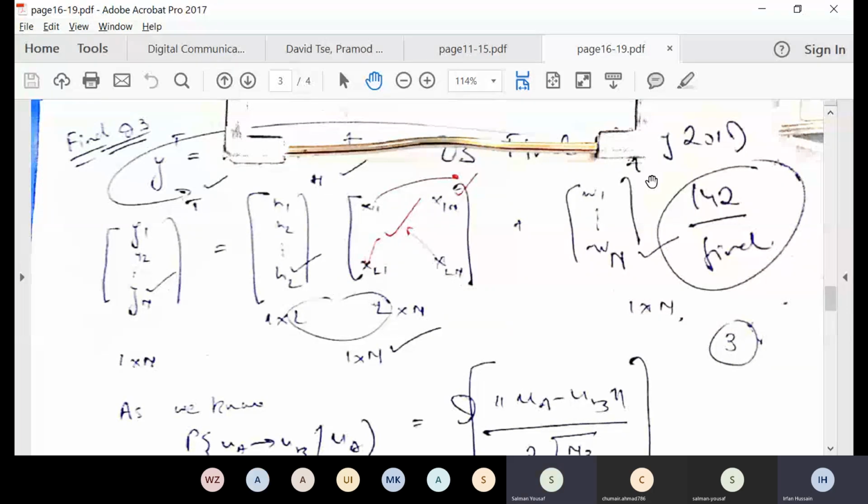I want a little clarification. Yes, good question. Sir, if we have schemes with orthogonal channels, then W will be CN. If we do only BPSK, or the linear ones like PAM, then it will remain N0, that is, real, where our orthogonal channel does not come in. Yes, I was saying in BPSK you are not utilizing it. Similarly, in simple PAM, as you're not utilizing the Q channel, you are right. You will be receiving only the single signal channel, because there is no use in doing all the analysis on the Q channel, the quadrature phase, because there will be no signal there. Yes, you are right.